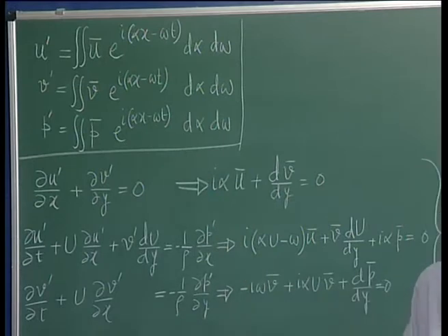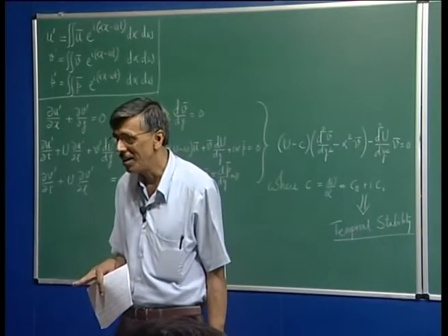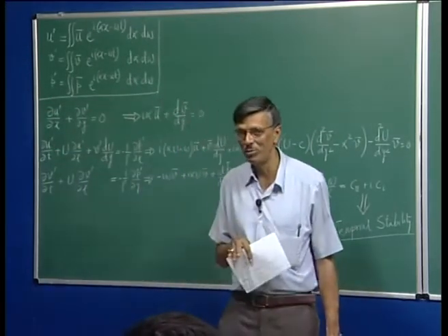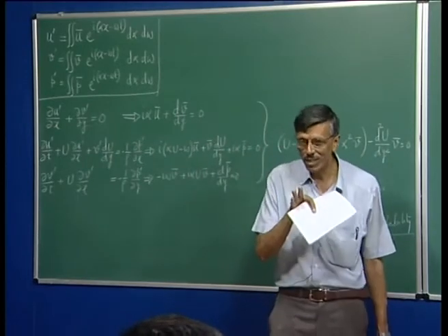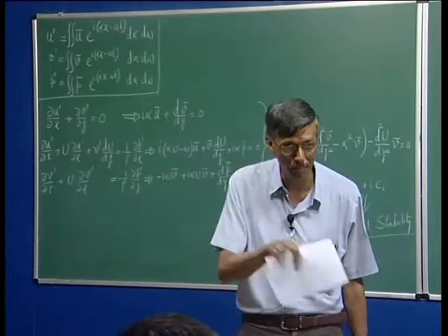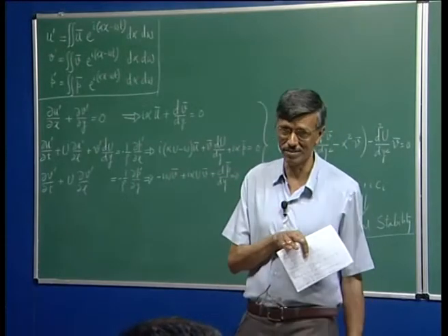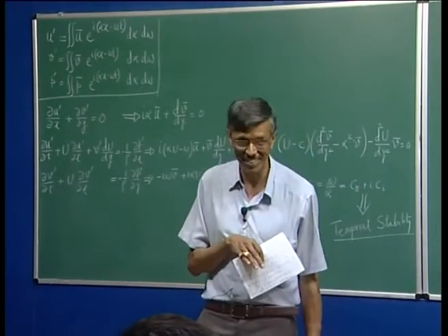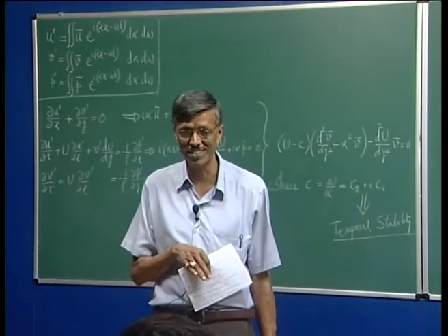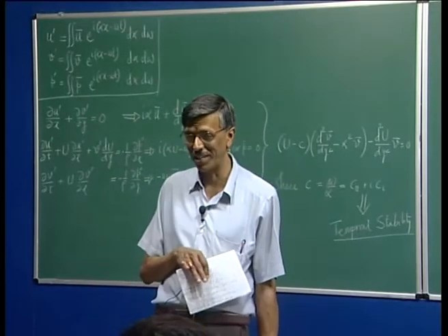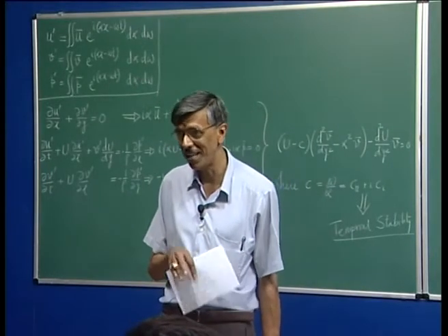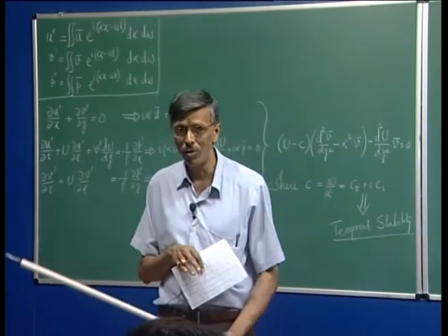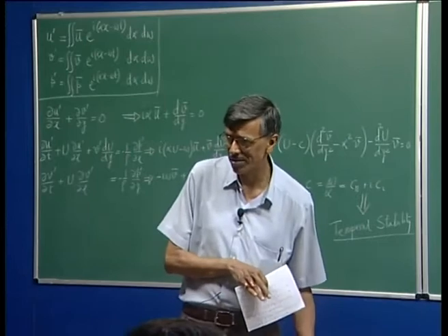So, if alpha i is negative and you are talking about x in the positive direction, then that corresponds to the stable solution, that will damp the solution. But please be aware that a priori you do not know if the disturbance has to go in the positive x direction. It can go in the opposite direction, negative x, right. If it does so, that same alpha i which I called stable for a downstream propagating disturbance will become unstable for an upstream propagating disturbance.